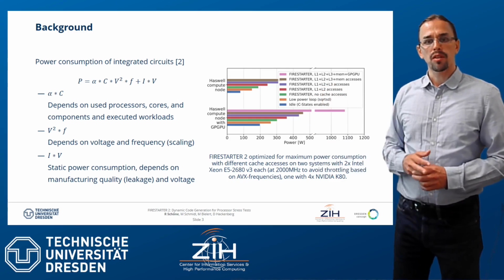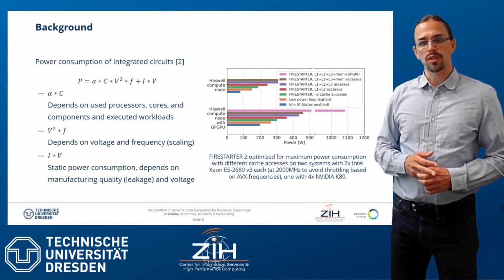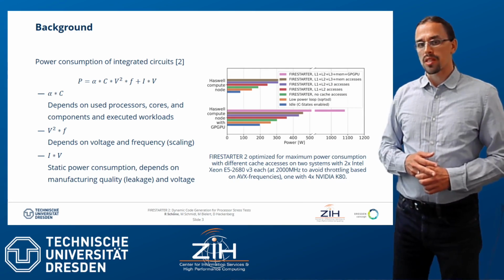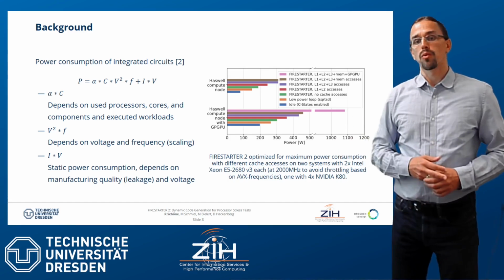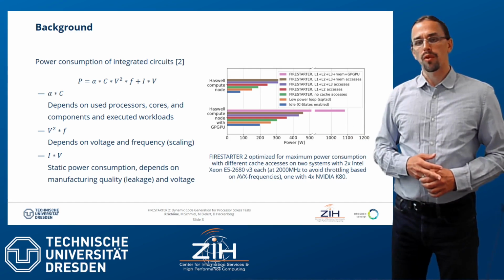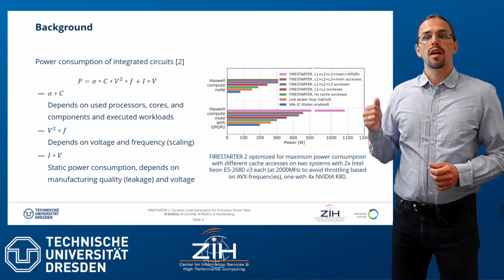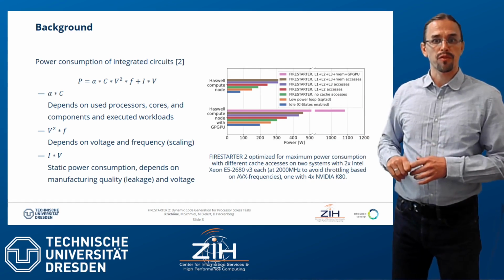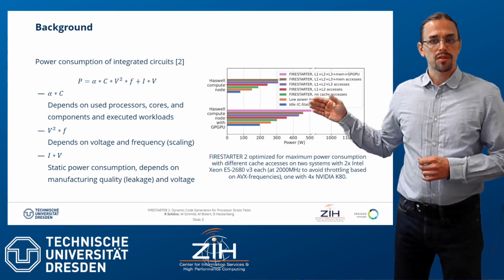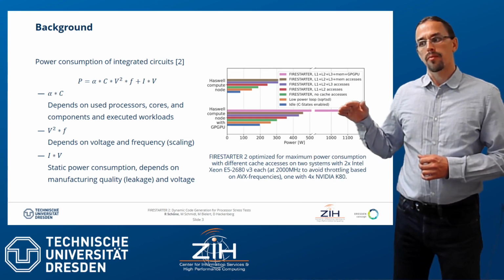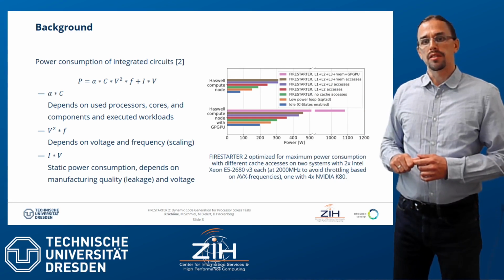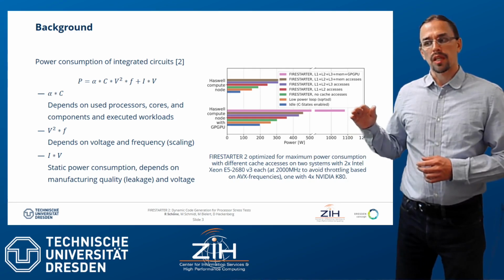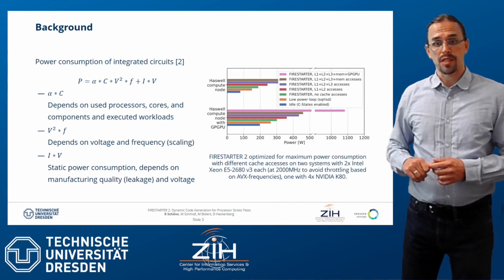Then the second part, that current times voltage, that's the static power consumption, which is then also influenced by idle states, which will decrease that I and the whole factor of that, and by the voltage, which is influenced by the dynamic voltage and frequency scaling, for example.